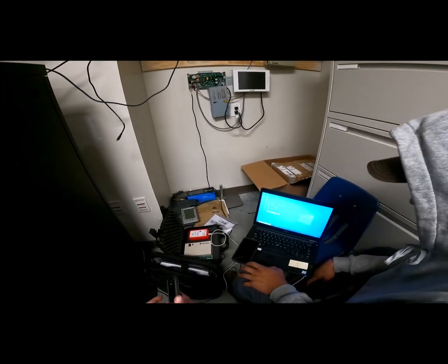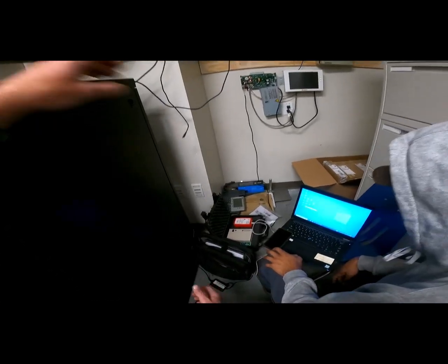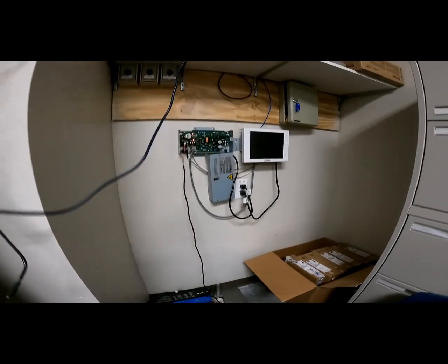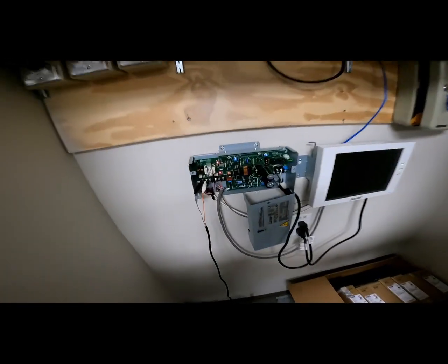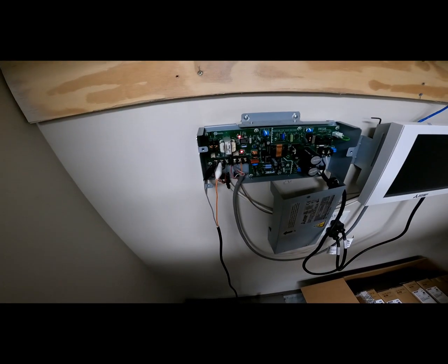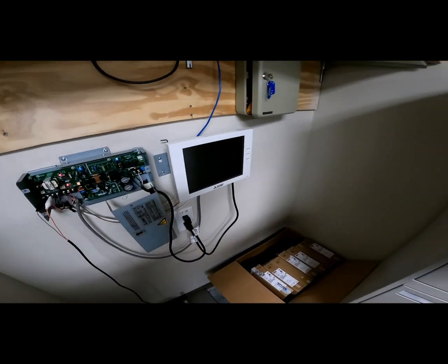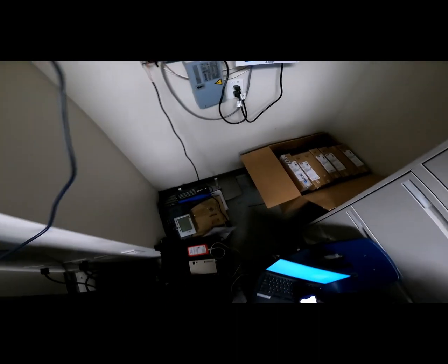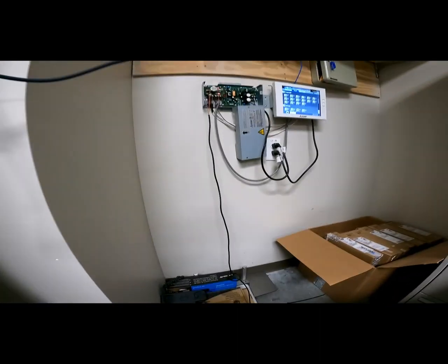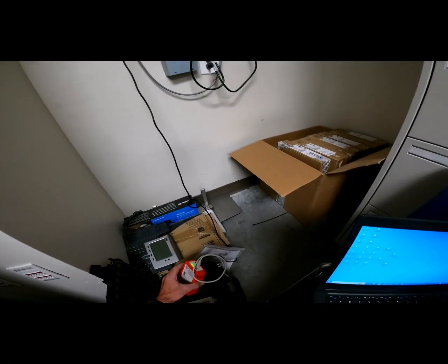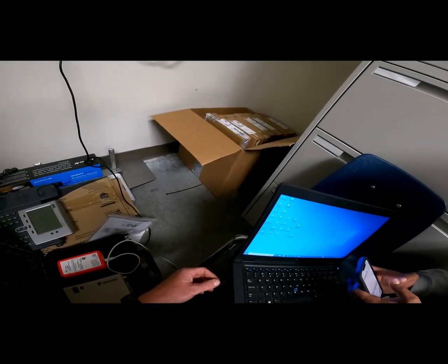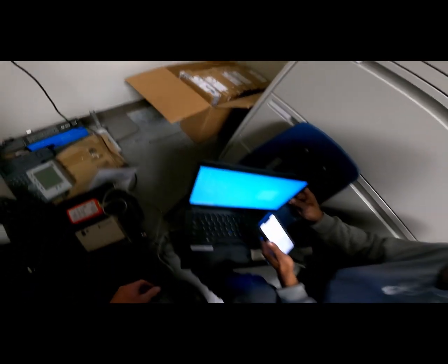So the first thing you have to do is get your maintenance tool attached to the M-Net. That's going to be your communication wires attached to TB2 on the control box beside the central controller. Your alligator clips will go to the M-Net. Your USB A to B cable will go into the back of the computer on a USB port, or wherever you have a USB port.